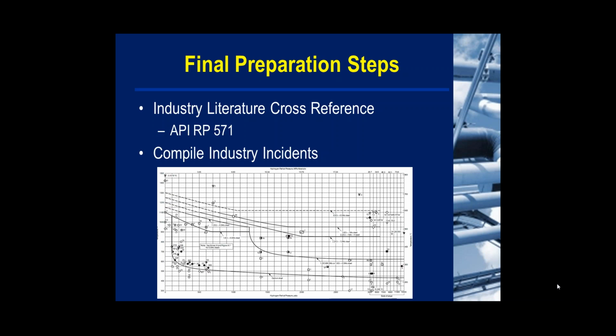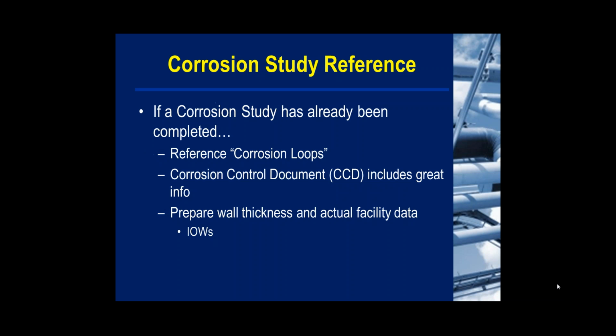So the first division is when you're sitting down as a facilitator, list out the entire PFD and all the materials that are applied here. For most refineries or separation processes, you start with a hydrocarbon feed, which is a mixture and separated into products, and different ancillary systems such as cooling water, glycol, refrigerants, hydrogen, among others. Each one of these should be listed as your first division for damage mechanism node development. And this step normally involves a facilitator and the process engineer.